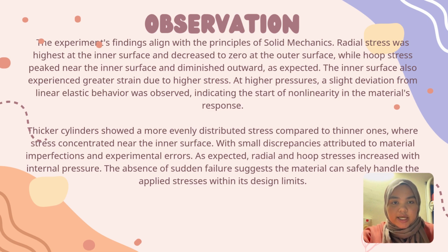At high pressures, a slight deviation from linear elastic behavior was observed, indicating the start of non-linearity in the material response. Thicker cylinders show a more evenly distributed stress compared to the thinner ones, where stress is concentrated near the inner surface, with small discrepancies attributed to material imperfections and experimental errors. The expected radial and hoop stresses increase with internal pressure. The absence of sudden failure suggests the material can safely handle the applied stresses within its design limits.